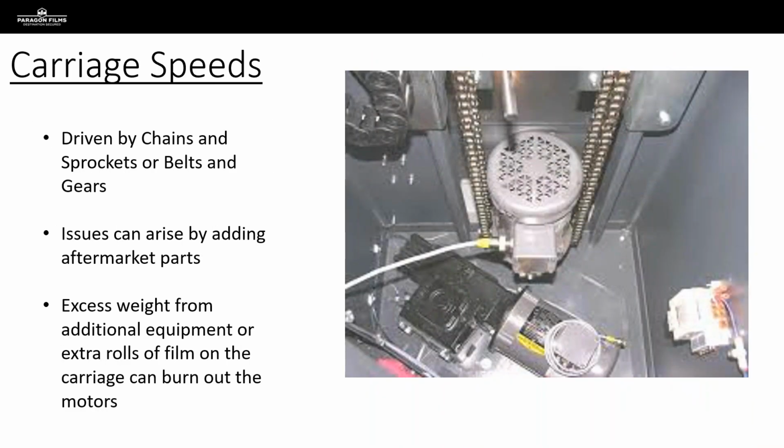So carriage speeds have a great effect on the overlap of the film, which greatly affects the on-pallet stretch, right? And the overall containment. So too fast of a carriage speed, especially with too high of a rotational speed, you're going to get no real overlap of the film with the pallet, which is going to really provide limited containment levels.